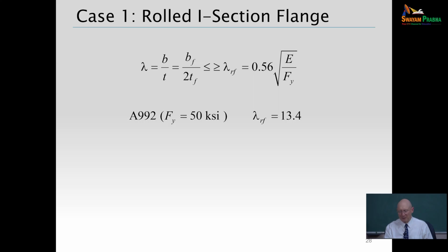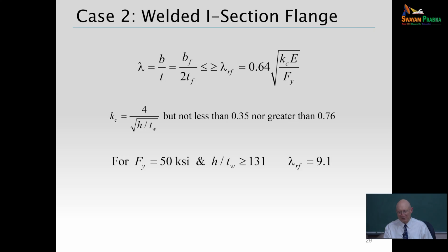Now, it turns out there are no rolled sections that have flanges that are grade 50 steel, grade 345, that would basically classify as a slender flange in uniform axial compression. I think that's there in case as we move to higher yield strength, and you have to have a pretty darn high yield strength before that would kick in though. Now webs is a different matter. Oh, wait a minute, I keep wanting to go to webs before I finish talking about flanges.